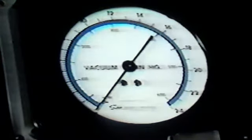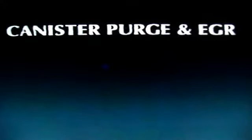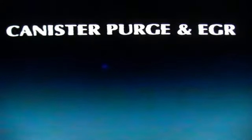To check canister purge, you disconnect the hose and use the vacuum gauge again. With the carb at the high step of the cam, you should see no vacuum. Sound a little complicated? It's not. Just remember that on the canister purge and EGR, you don't want any vacuum reading, and on the EFE, you do. It's that simple.